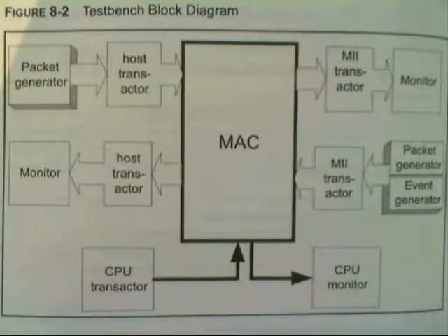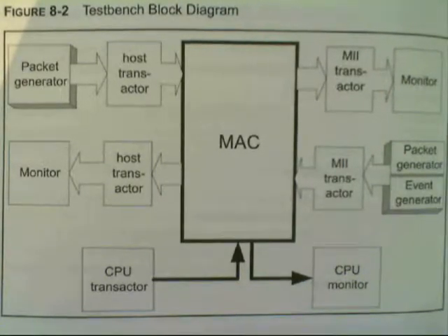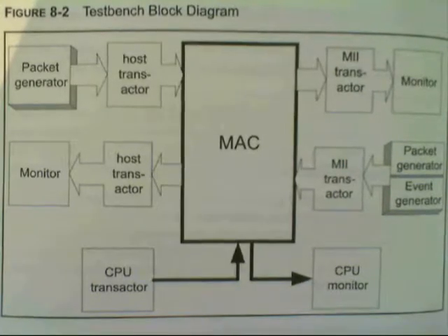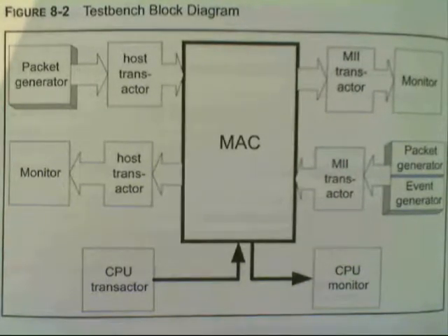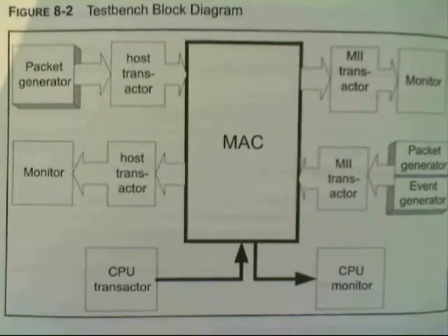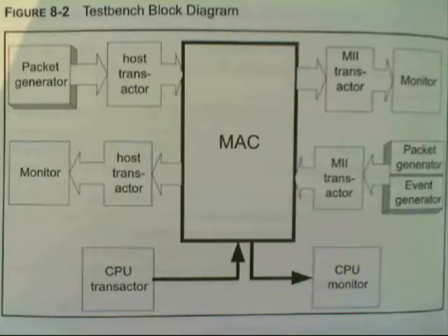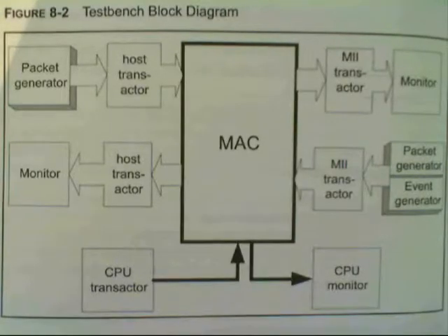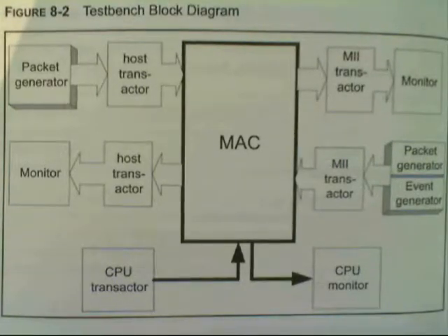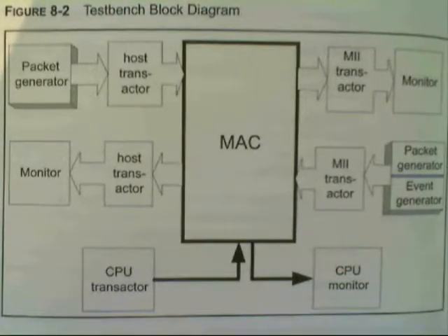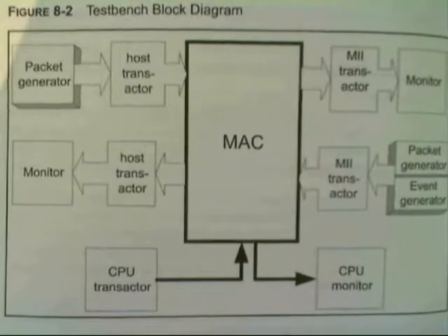Functional verification for the MAC core is performed with automatic stimulus generation and randomized testing. For stimulus generation for the MAC controller, the test is divided into three categories: normal, transmit, and receive with errors. An important element of the MAC verification process is controlling packet distribution, packet size, the MAC destination address, alignment errors, and CRC error packets.